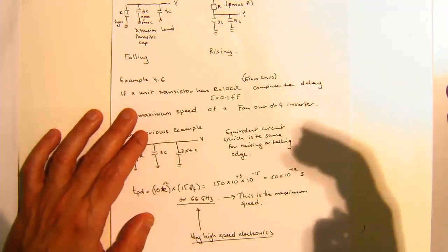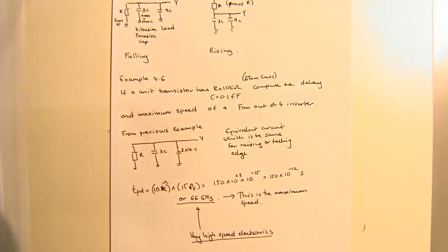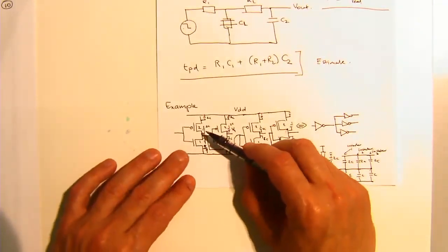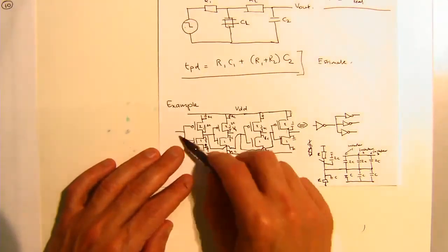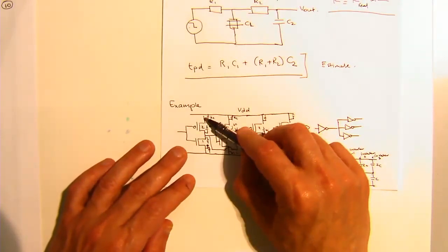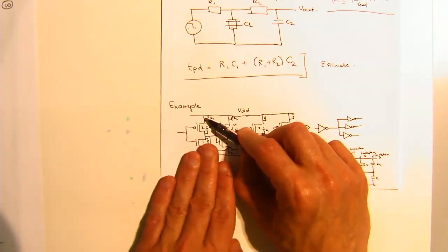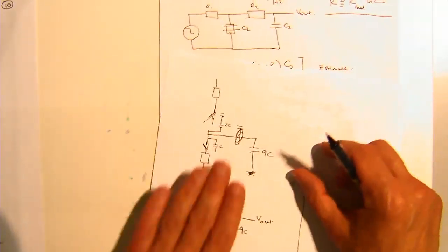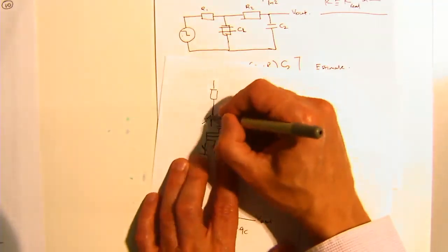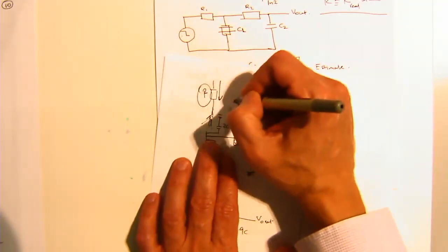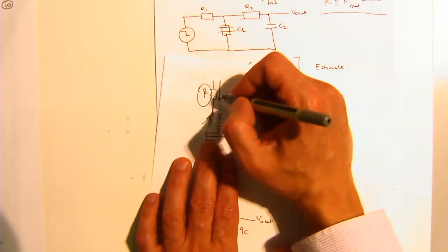And that's why I wanted to make sure I was emphasizing what was actually happening. For example, if you're going from a 0 to 1, the NMOS device is off, right? So that switch down here is off, and this switch is on. So therefore, it's this R that's part of the circuit. Is that clear? Okay.